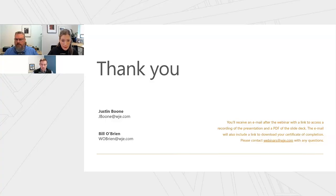Okay. At what stage in the construction process do you recommend testing, before or after the exterior cladding is installed? Sure. So in a perfect world, you would do it before the exterior cladding was installed, once the air barrier is complete and you've got all your door seals and all your windows in. Unfortunately, the way that sequencing for most commercial construction, or most construction in general, works, it doesn't quite go in that order of operations.